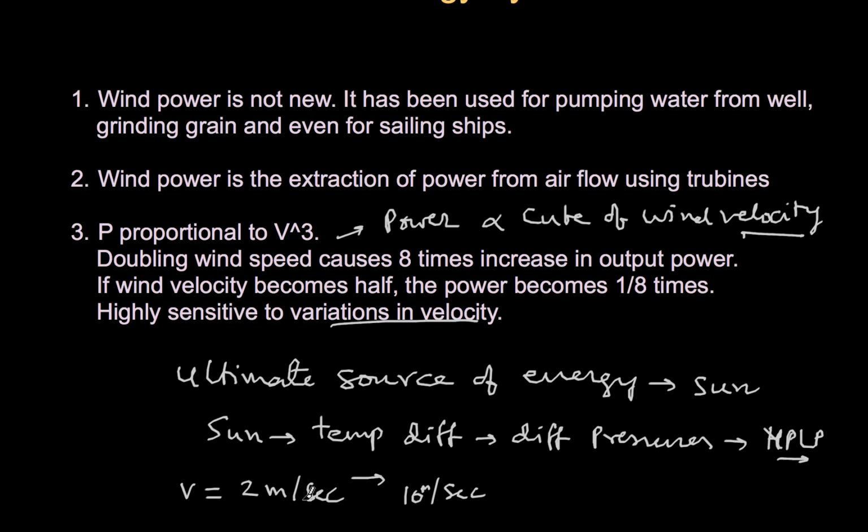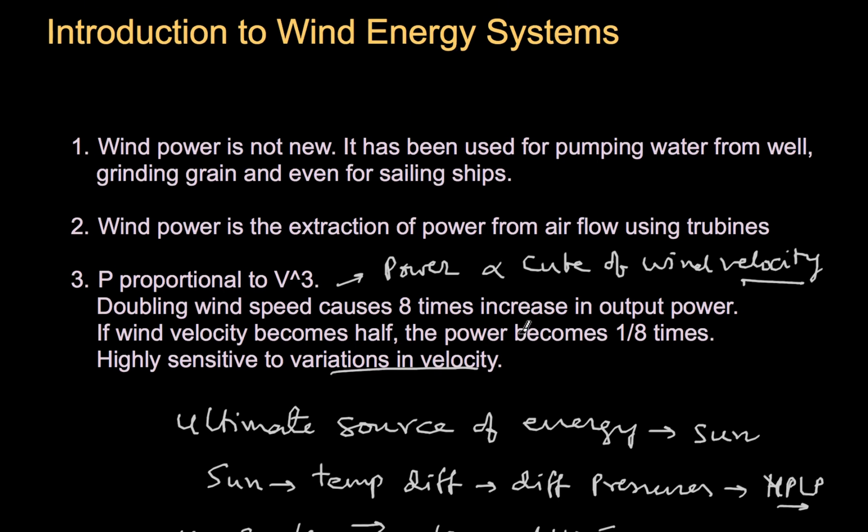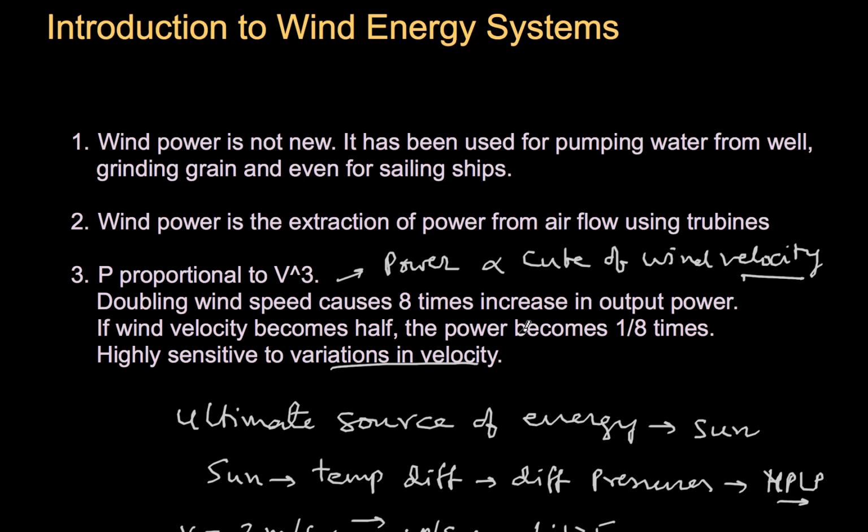So what would the power be? Because the velocity is 5 times more, the power hitting your face would be the cube of 5, so it will be 1 is to 125. The cube of 5 is 5 into 5 into 5, which is 125. So you are actually getting 125 times the power when you compare 2 meters per second and 10 meters per second. So it is highly sensitive. I've given only an example, since you might have that physical experience of breeze hitting your face. But it is highly sensitive to the velocity of the wind.